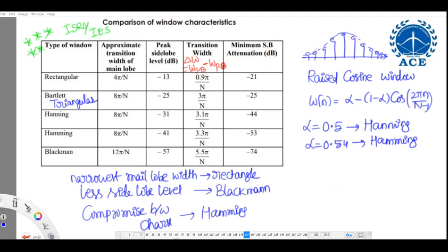If phase is not a concern, you can go for IIR. For the given specification, if you want to reduce the order, FIR can also have magnitude approximation, but if FIR is asking for a 15th order filter, the same problem with IIR is possible with third order. There are 10 parameters to be compared before starting the design. Then you will know which is best suited. We cannot decide directly. For your understanding at this level, I told you one point: magnitude approximation means IIR, linear phase means FIR.